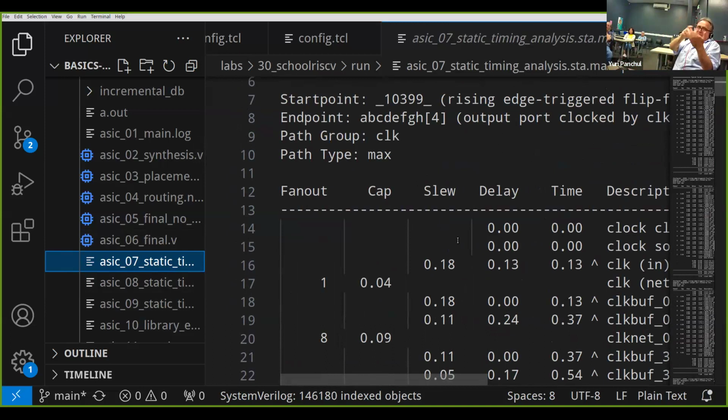And in order to do this, all logic actions take time in hardware, in picoseconds. So it knows that before you choose a value in a multiplexer, you need to spend like 20 or 40 picoseconds. Then you need to do another action in order to add things. This may take like 80 picoseconds to add a couple of small values, and all this path should be done before your clock goes from 0 to 1 again.